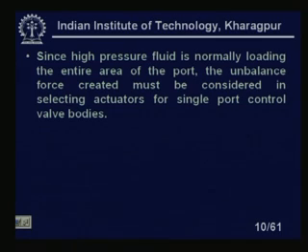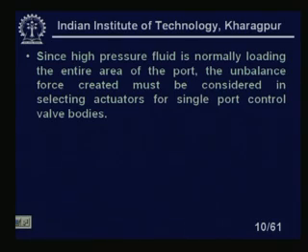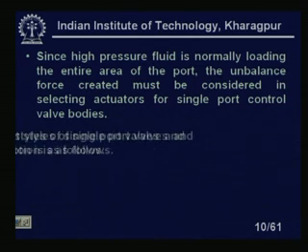Since high pressure fluid is normally loading the entire area of the port, the unbalanced force created must be considered in selecting actuators for single port control valve bodies. If the liquid is coming at high pressure, quite obviously it will occupy the entire area of the inlet port of the valve, and the unbalanced force created must be considered in selecting the actuators for single port control valve bodies.